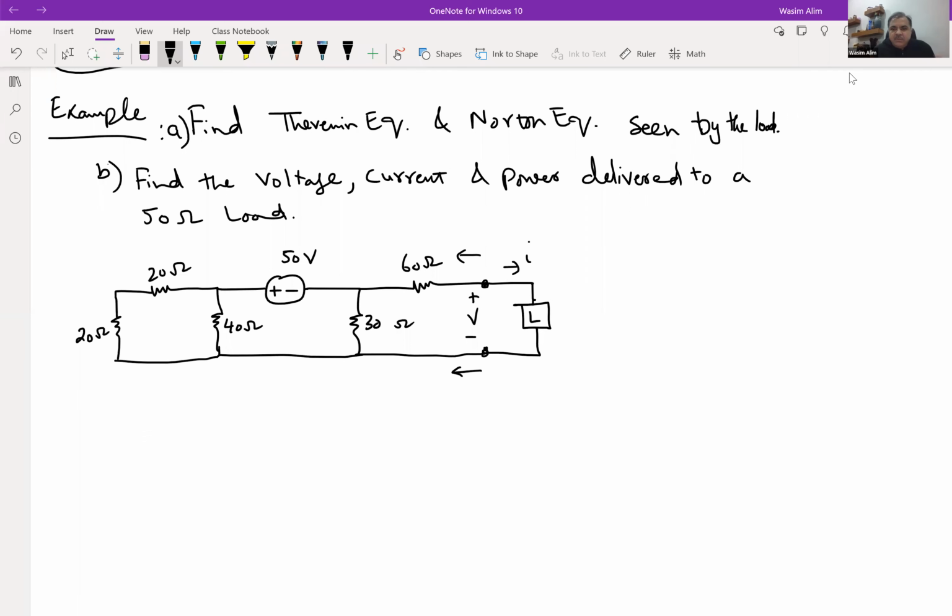So that sort of brings the right-hand side to a more standard form that we're used to, where we see that there's some source voltage on the right-hand side, and then there is some rest of the circuit like that, right? So we want to bring it to that form so that it's a little bit consistent with what we're used to, okay? So the first thing we want to do is combine the two resistors.